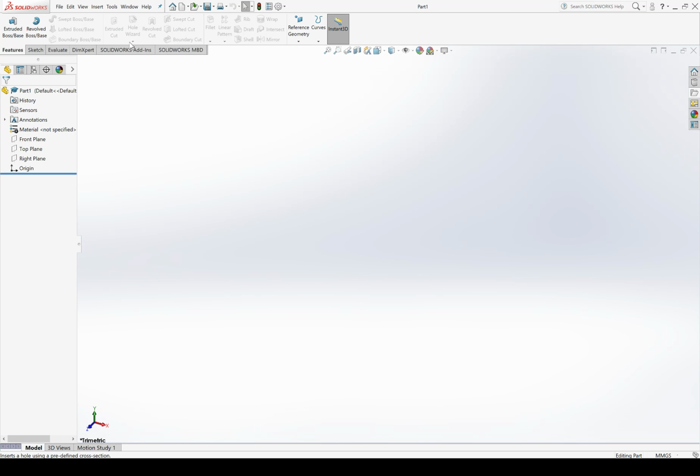If we wanted to make that, we have to start with a drawing of a square, and our drawing has to be on a plane. Our drawing is going to be created inside of what SolidWorks calls a sketch. So if we click on the Sketch tab, one of our options here is Sketch. If we click on Sketch, that's the leftmost button under the Sketch tab, that'll create a new sketch, and it'll ask us what plane we want to create our sketch on.